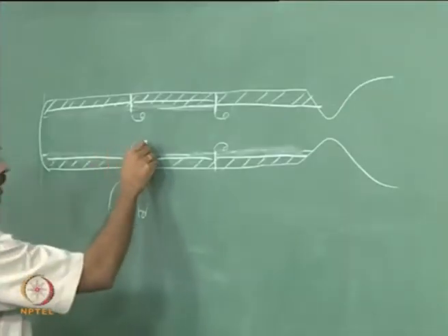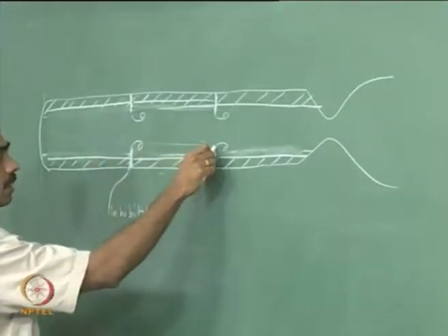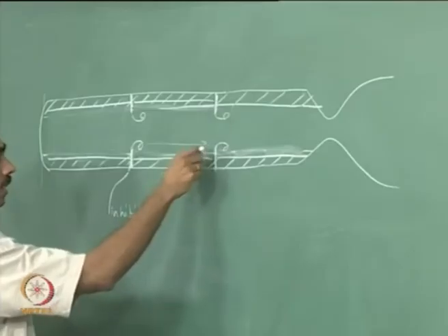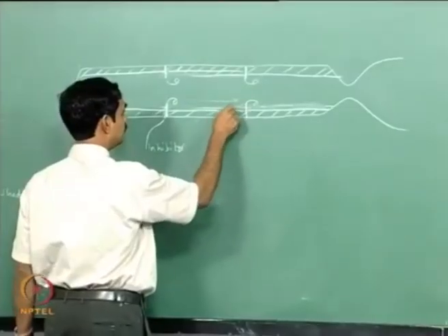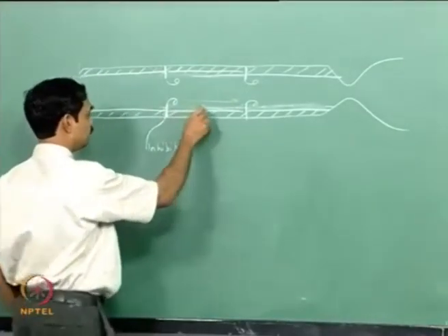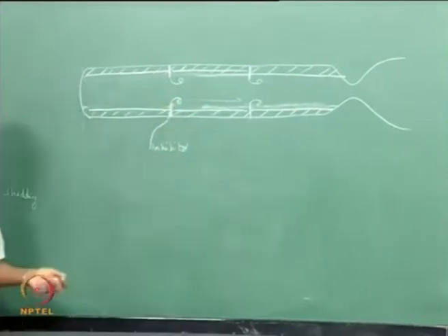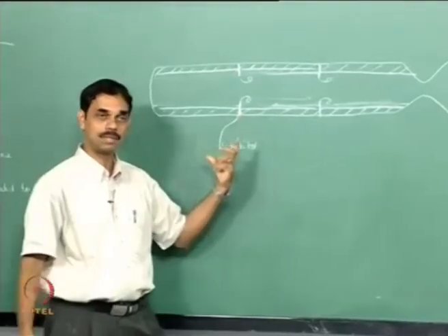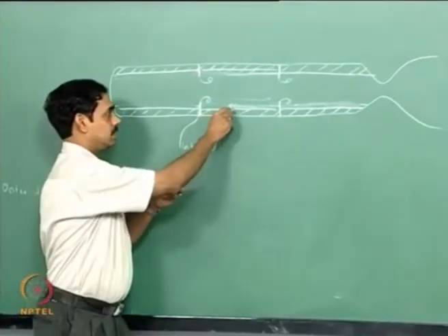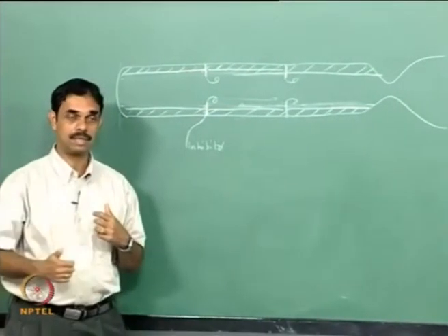This vortex that is shed will come back and come here, and right as it comes here the next one may be shed, and as it impinges here you send the acoustic wave back, and this gets into a feedback. Normally it sheds at some frequency, but under the lock-on circumstance the acoustic wave reinforces the shedding, and then you get loud amplitudes.